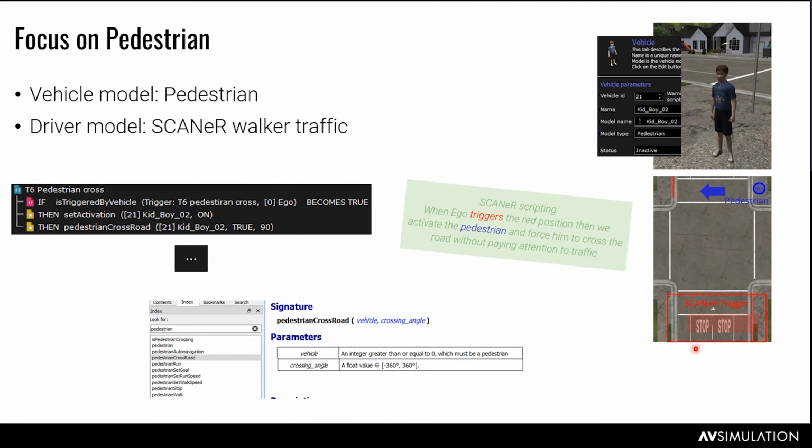So in this case, this is the trigger. I put it right at the stop line. Once I'm inside this trigger, I can also specify which vehicle is going to trigger this rectangle. So if the traffic passes this trigger, I don't want it to be active, only when my ego vehicle does it. It's very easy. It's all GUIs. You don't have to program anything. You can just select the vehicle you want to be filtered by the trigger.